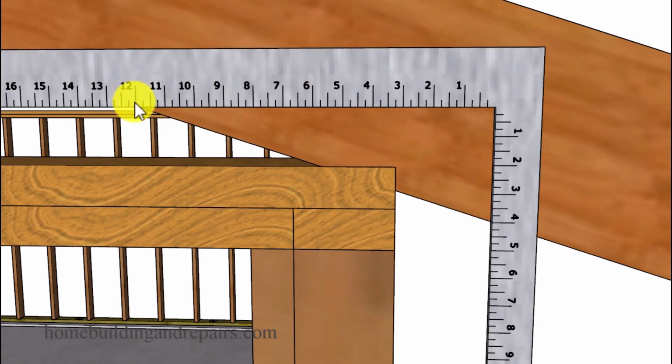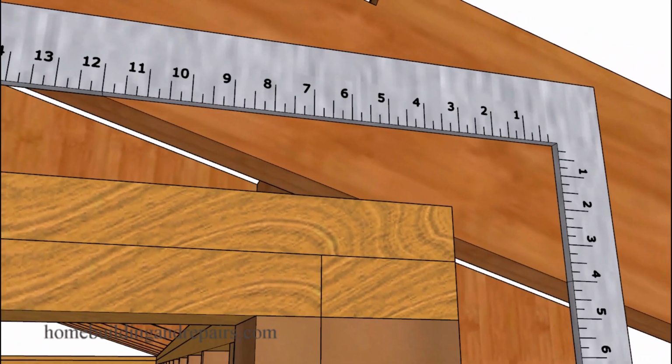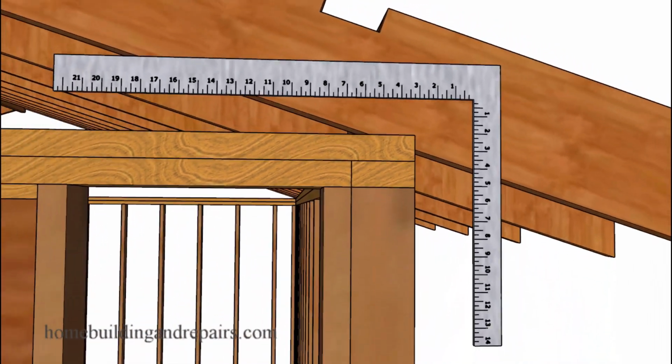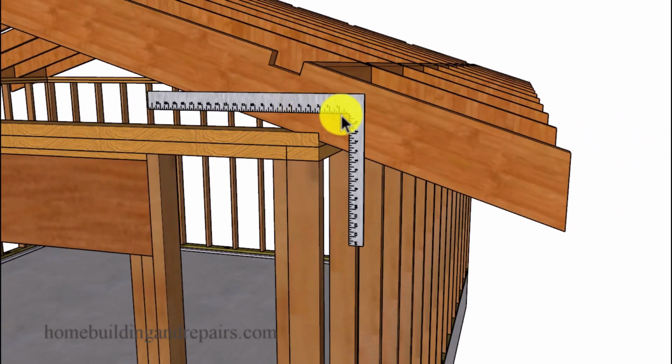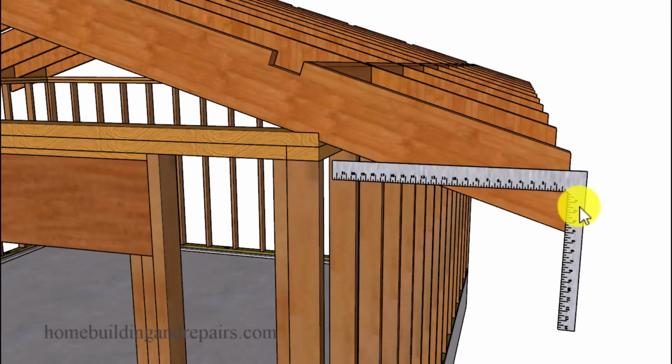And to figure out the angles for those cuts on our roof rafter, we're simply going to line the framing square up with the edge of the roof rafter with the 12-inch mark on one side and the 4-inch mark on the other side. And if I was going to use a 6 and 12 roof ratio, I would leave the 12 alone and move the framing square to where the 6 would be positioned at the edge of the roof rafter instead of the 4. So basically, any vertical measurement or horizontal measurement after the roof rafter has been installed will be able to be created by using this example here, including the fascia board plumb cut angle.